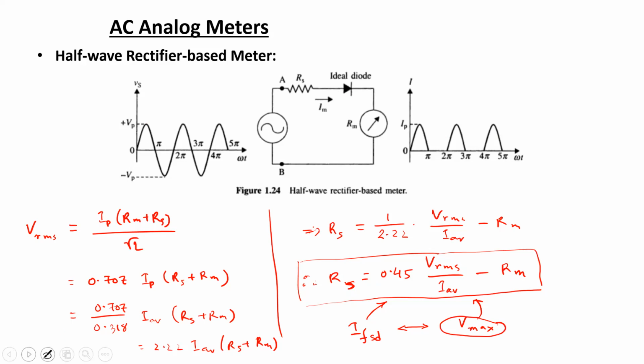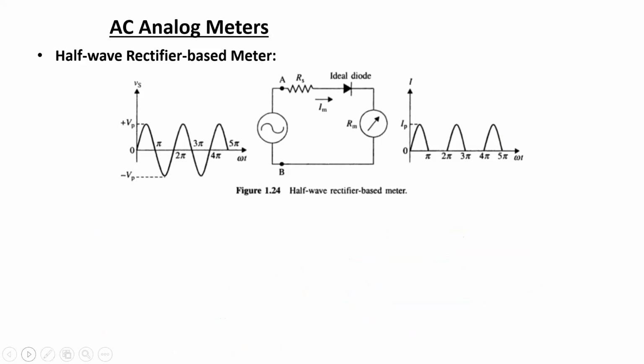Now, moving on, let us discuss a few problems that are associated with this particular form of the circuit. One of the problems is that in case of negative half cycle, as we are considering the diode to be operating as an ideal diode, we have considered the current to be 0 in the negative half cycle, because the diode is reverse biased, forming an open circuit.